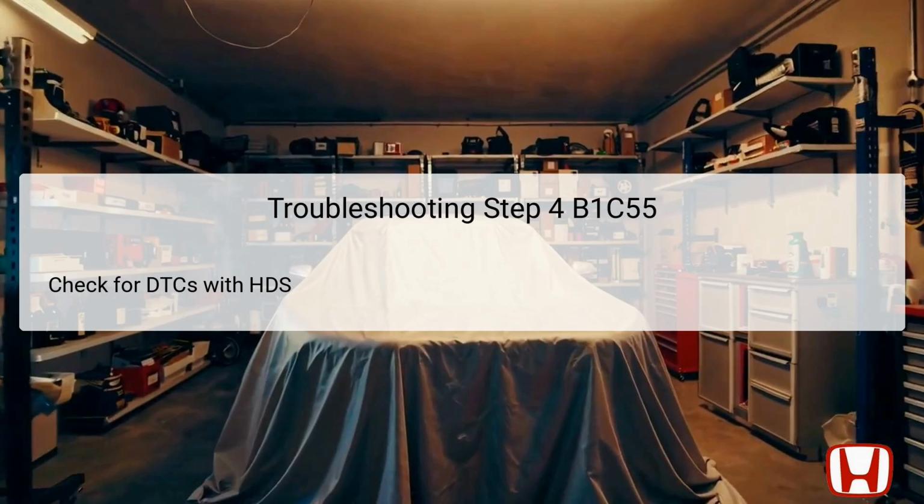causing sporadic issues. The fifth step in the troubleshooting process for DTC B1C55 involves turning the ignition switch to the lock, 0 position once again. This action is crucial as it signifies to the vehicle systems that you are preparing to conduct further diagnostic checks. By turning the ignition off, you effectively enter a state that will allow for safe disconnections and reconnections of the vehicle's electrical components without risking damage or accidental activation.